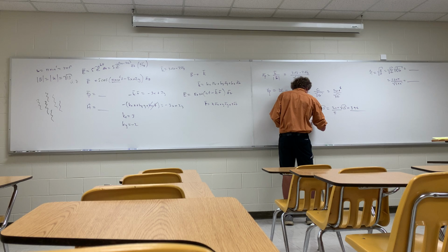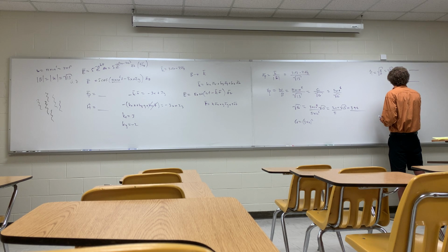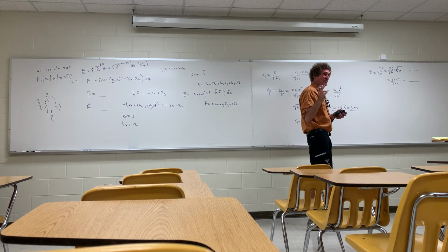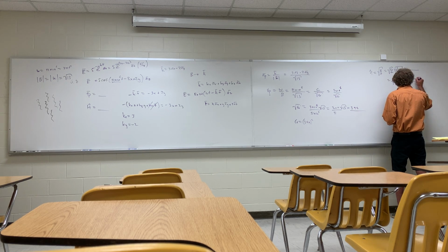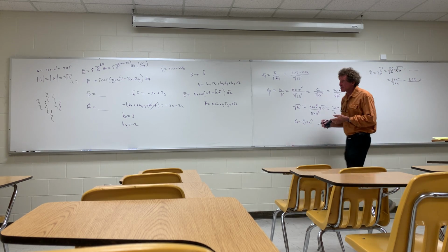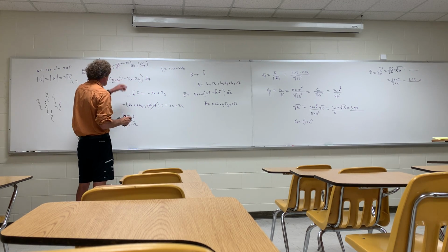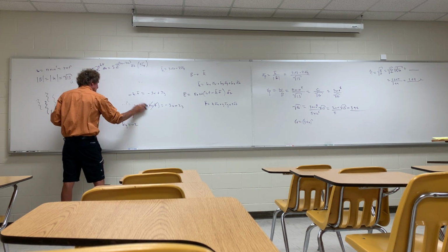So it would be 125 over 344, actually, right? That's just about 1, if you look. What does it come out to? About 1.09. Okay, 1.09 ohms, and that means now I can get the actual value of the H field, because I have the phasor form of the E field right here. So to get the phasor form of the H field, I'll put it right under here, and then we'll get the time domain form.